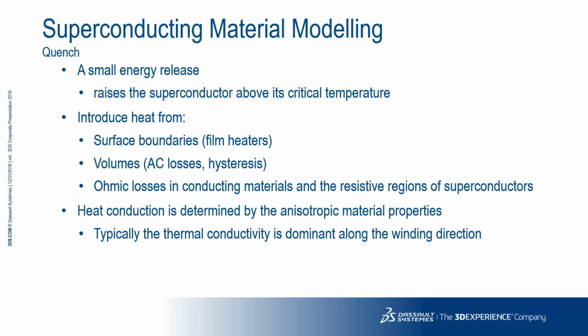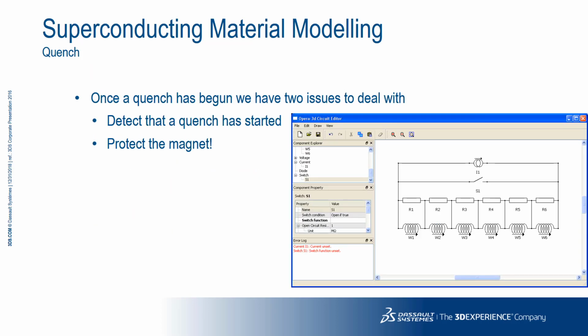To this point, in this section, discussing the modelling of superconducting materials, we've looked at only the electromagnetic properties of the coils. However, in superconducting systems, often the thermal and structural properties are also of interest. One such situation, as described earlier, is that of superconducting quench. Here we're simulating the transition from superconducting to resistive states driven by the propagation and generation of heat in the device. In an AC system, it's much more difficult to detect and hence protect against due to the slower, smoother transition from purely superconducting through mixed to resistive states.